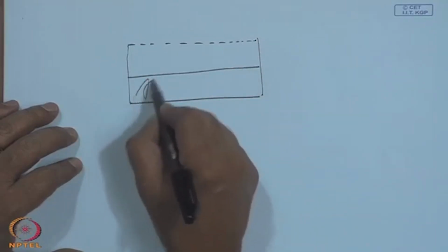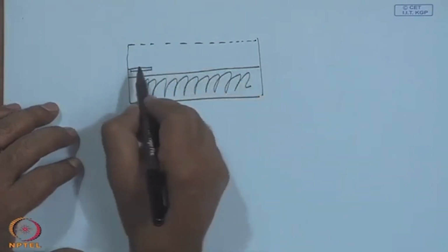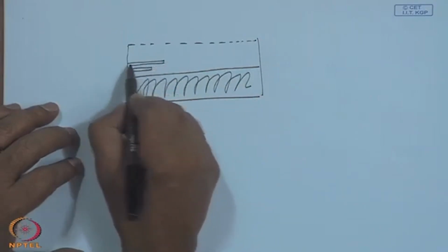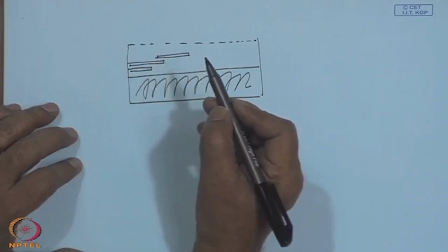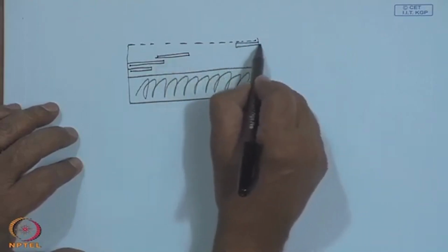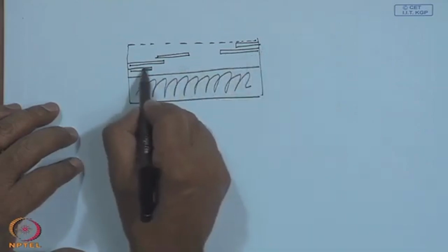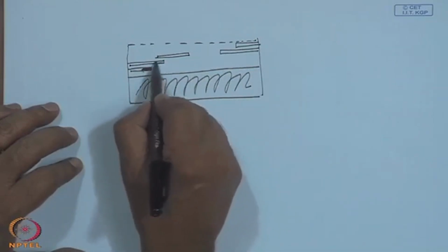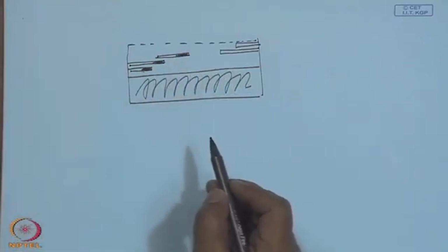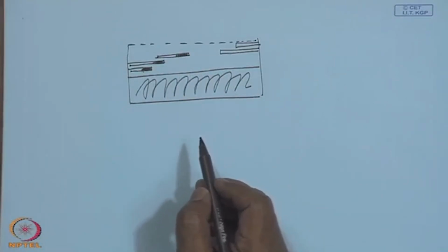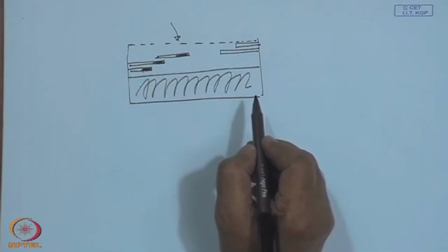This bottom is insulated, and you have got plates, then another here like this, up to here again last, then this may protrude a little more with a black painted portion and a transparent portion, one overlapping the other, so that the transparent portions will be transmitting the solar radiation falling on the top surface, whereas the black one will be absorbing the solar radiation.